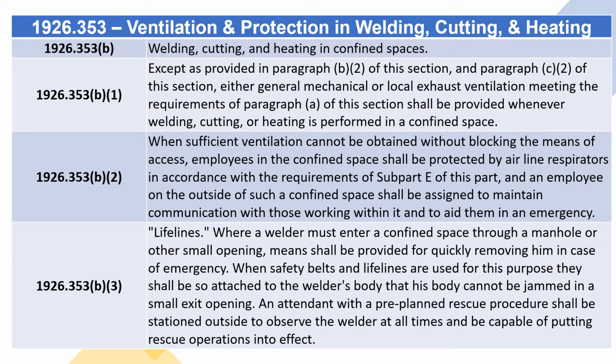B.2. When sufficient ventilation cannot be obtained without blocking the means of access, employees in the confined space shall be protected by airline respirators in accordance with the requirements of subpart E of this part, and an employee on the outside of such a confined space shall be assigned to maintain communication with those working within it and to aid them in an emergency.